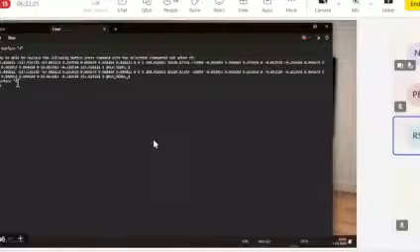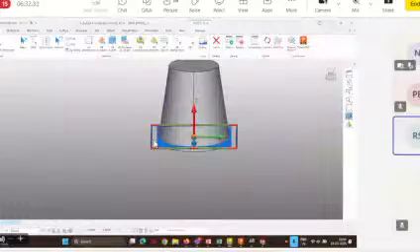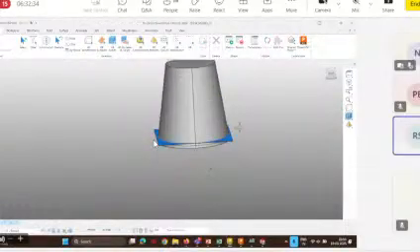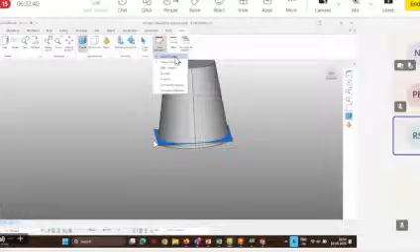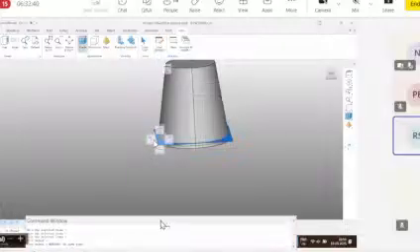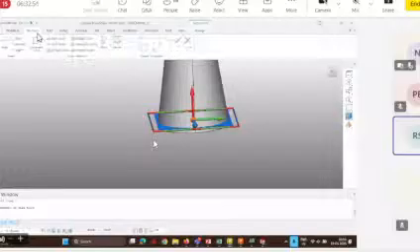Or maybe the first surface I selected, and I keep on adding in a loop, inside this loop only this Z5, and within this loop if I write the intersection command as well, then I can make the entire process automated. And if you want to see the command for this, you can go to user interface and open the command window, and right now I can see nothing is there. So if I do some operation, it will pop up over here.